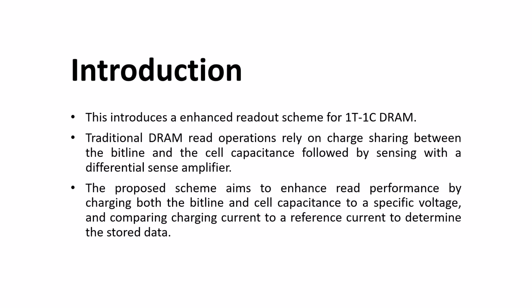Next, the primary principle of this proposed scheme is the charging of both the bit line and the cell capacitance to a specific voltage, and comparing this charging current to a reference current using a current comparator. If the charging current is less than the reference current, then it will be sensed as logic 0. If the charging current is greater than the reference current, then it will be sensed as logic 1.